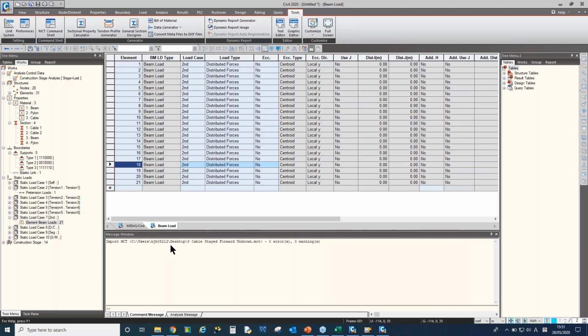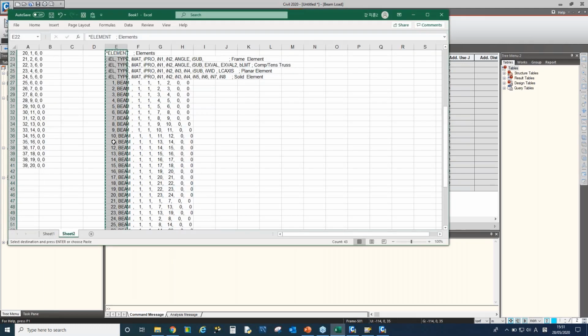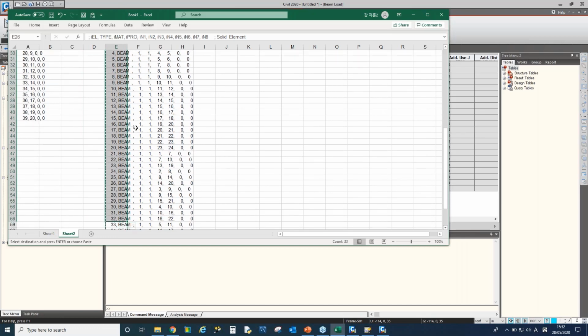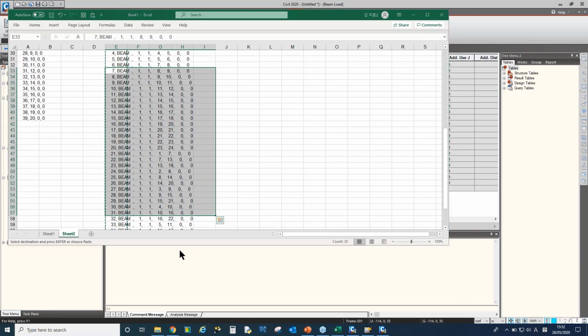Does MIDAS contain a VBA editor? Actually, we don't have a VBA editor. I saw some people using a VBA tool to generate all the text. So we have one more step to use VBA. Using the VBA tool, you can create some macro or software to generate the text format. After generating all this text, you can bring it to MIDAS Civil. I hope this can be your answer.